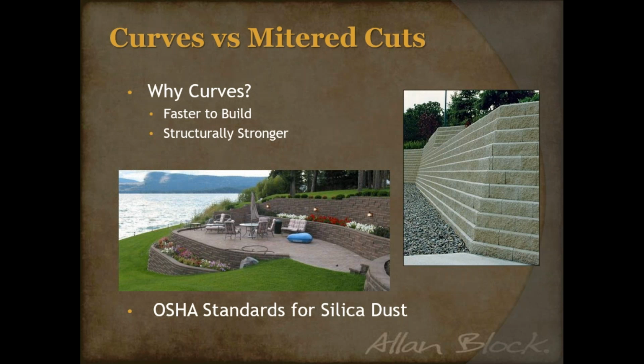That is a joint in the wall that's going to create a vertical seam all the way from the first course to the last course. What you see here, and if I get my pointer out, is a mitered joint right here in that wall. They did a pretty good job, but you've got two different walls trying to go opposite directions.